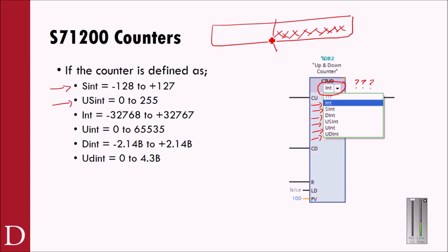And so here's my mark, and I can be plus 10 or minus 10 from that target point, right? So I can keep a value of, oh, I'm 5 below where I want to be, or I'm 5 above where I want to be. In that case, I might want to use the signed integer, which is going to give me a range of -128 to +127.